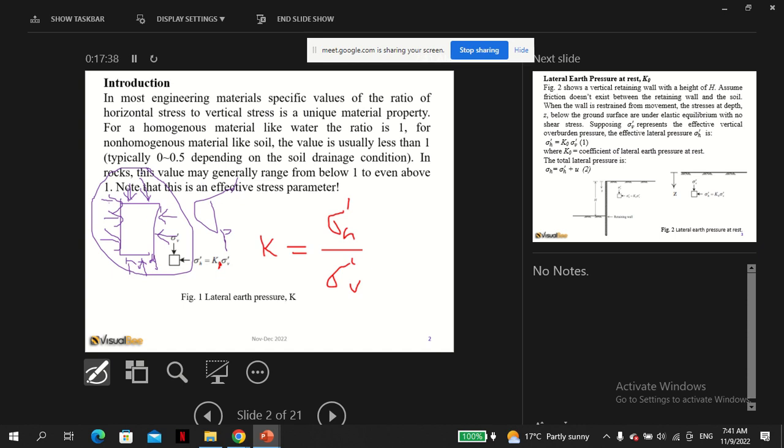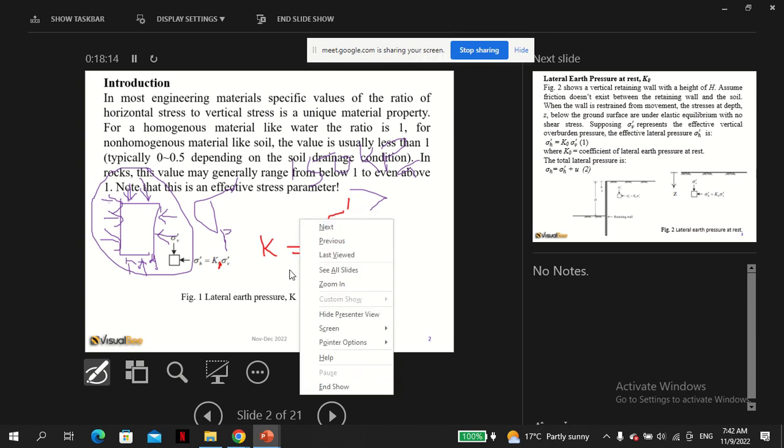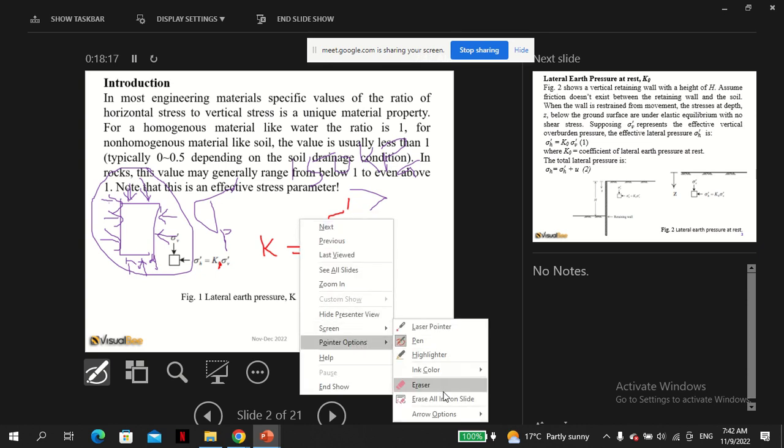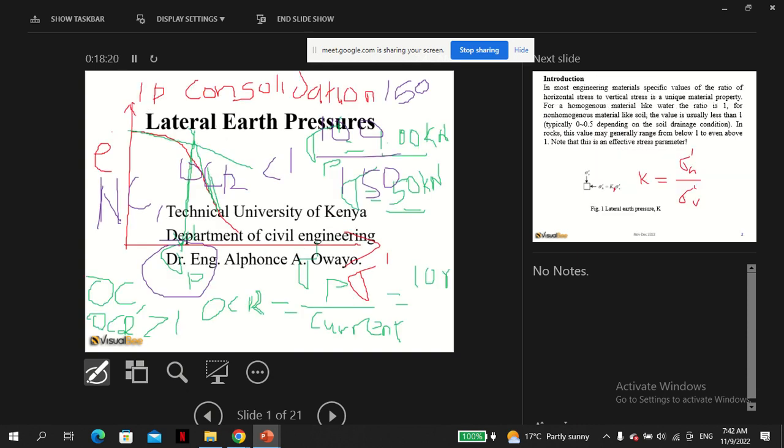And what is done in the process of consolidation, if the value you're going to use for consolidation is 150 kPa, the pressure is applied one step at a time. So the machine will apply one uniform pressure, 2, 3, 4 until it reaches 150. So when it reaches 150, assuming 150 is greater than sigma p, then beyond that it becomes what is called normally consolidated soil. That's what we want for this experiment. That means the stress history effects have been erased by the loading.